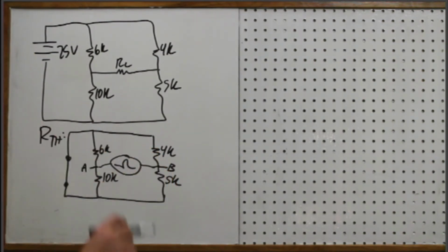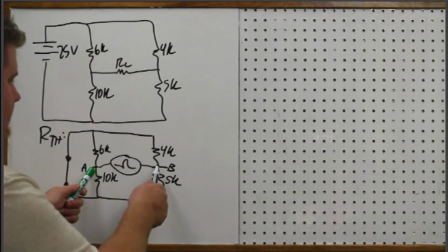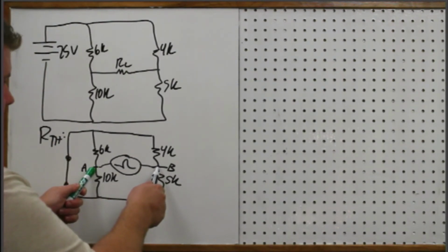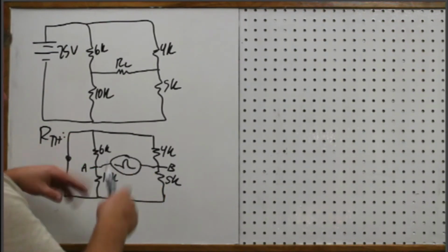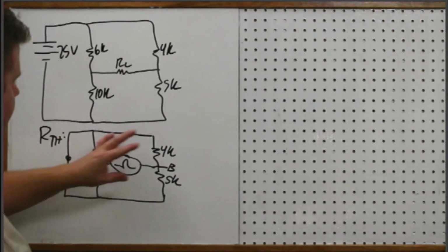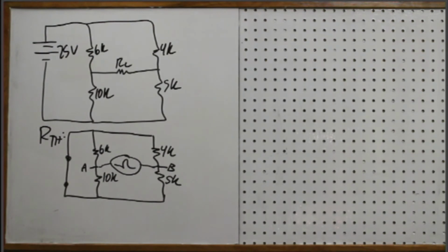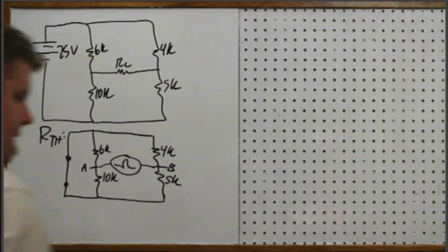You have to remember, the probes are now at two random points in the circuit here. So that's what everything is referenced on, okay? So you can't just add everything up and then take them in parallel. Like you can't just take this branch, 16 in parallel with 9 and get the answer, okay? So this is how we have to do it.